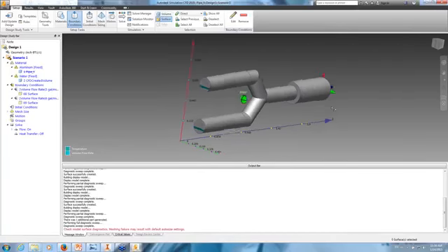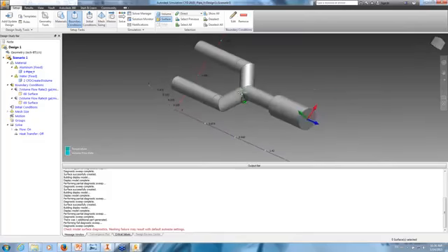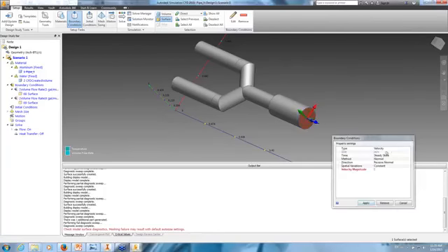I will rotate. Now if I try to solve this without specifying an outlet, you're not going to really get anything out of it. To specify an outlet, we typically set the pressure to be equal to 0.